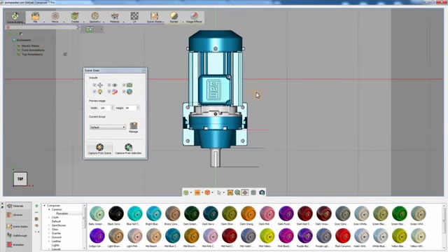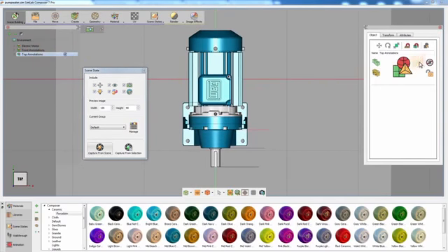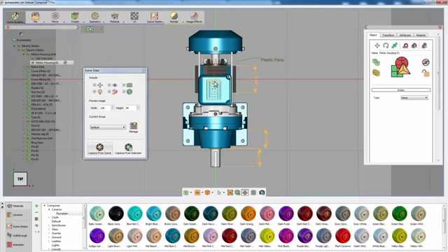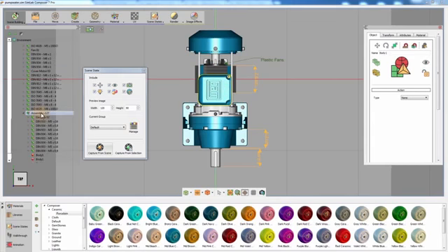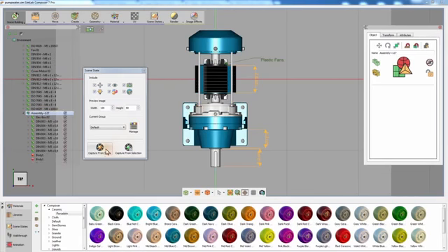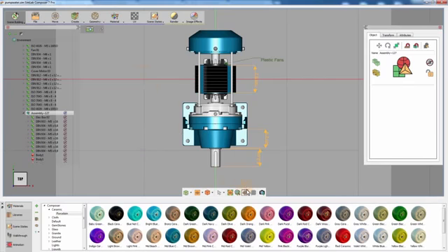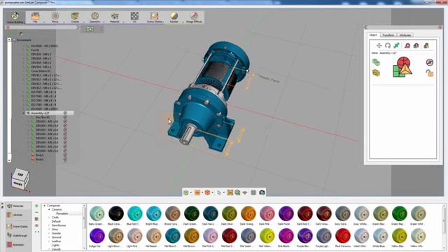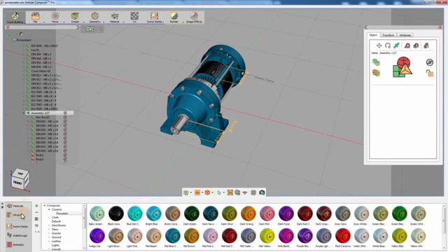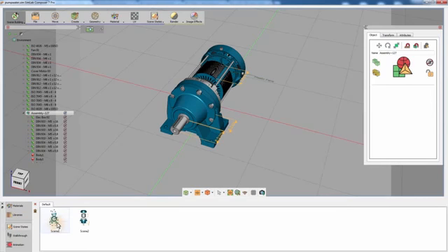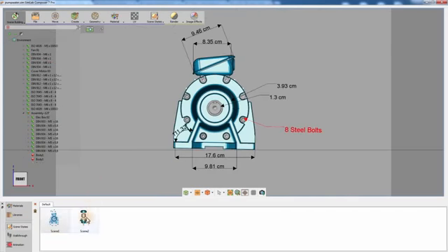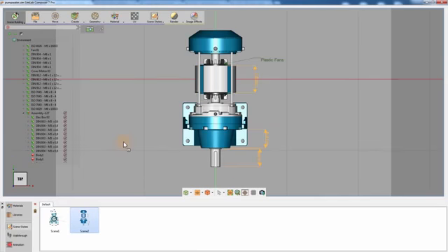Switch to a top parallel view. Hide the electric box in the hull and click on Capture Scene States again. Go to the Scene States tab in the panel at the bottom and you will find the captured scene states there. Drag the thumbnail of the scene state to the scene to apply it.